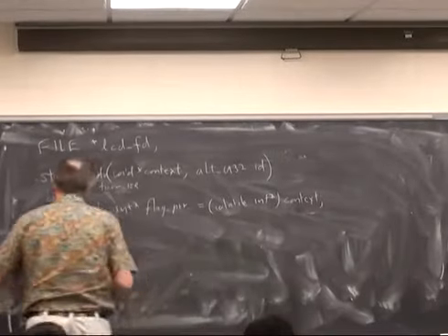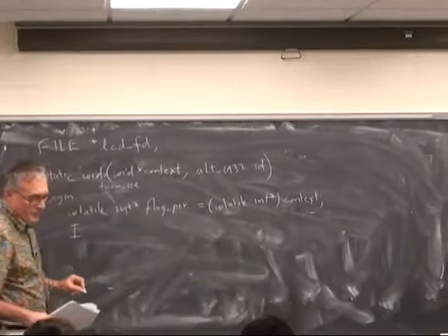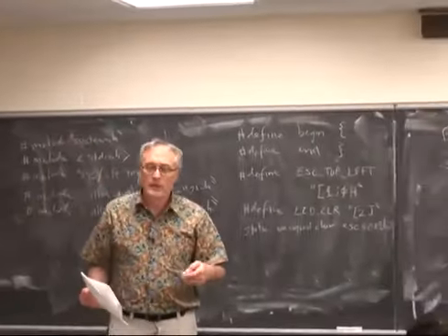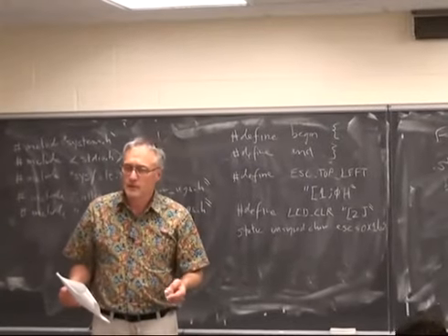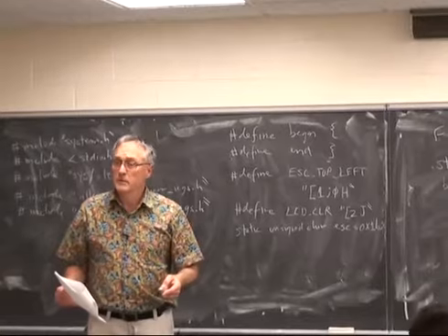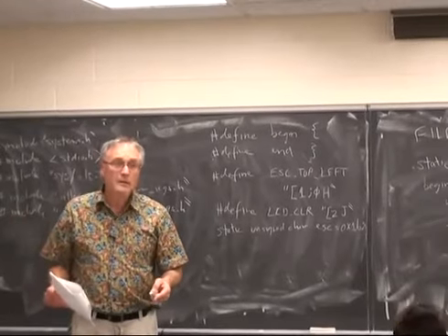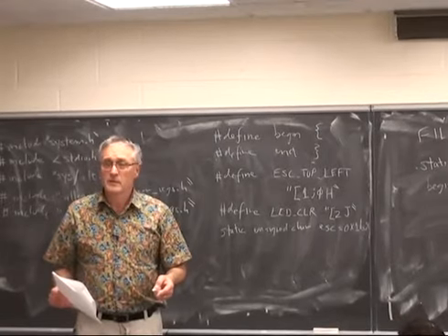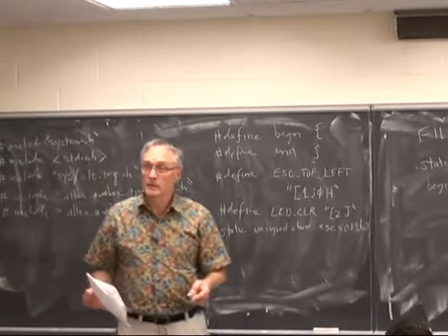Now, the very first thing we have to do, the very first executable code in an interrupt service routine, is to reset the interrupt flag which caused the interrupt service routine to fire, because the microcontroller does not do that automatically. And if you don't reset the flag, as soon as you exit the interrupt service routine, it'll take another interrupt.